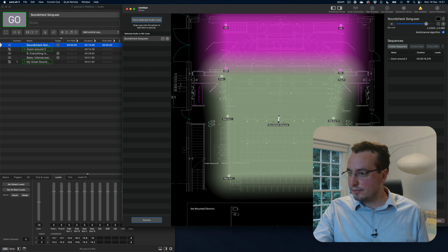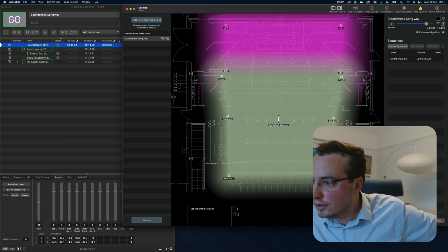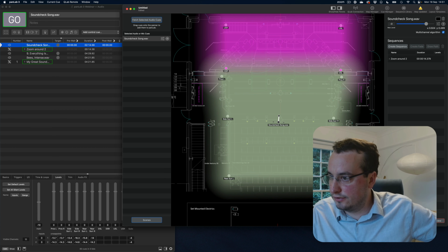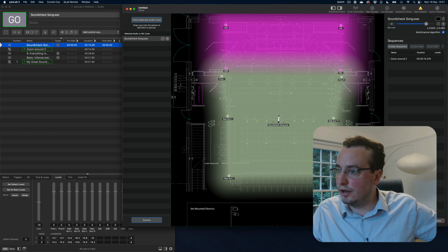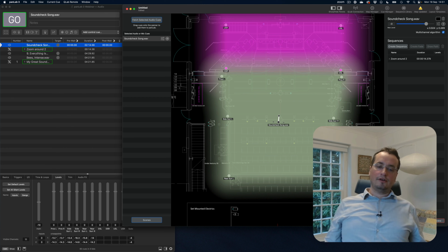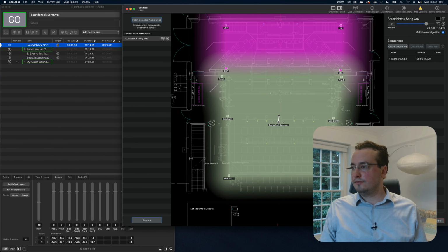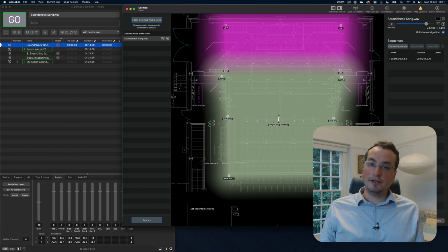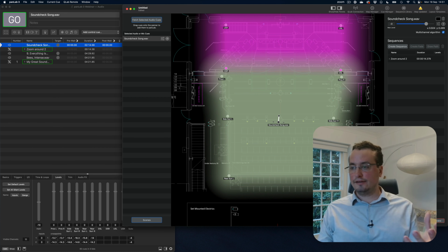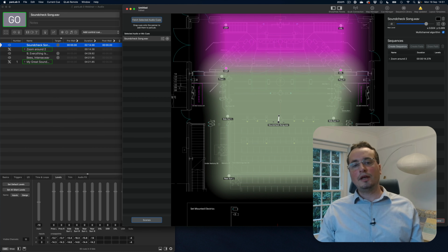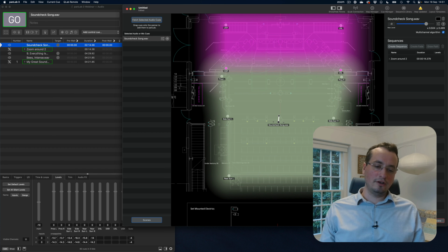Any more questions before we end this up? Okay, yes. Would it be worthy to introduce delay time parameters applied to the cue outputs as well as the audio level parameters within the movement of a sound object? Yeah, good question. So this is purely amplitude-based panning. And there's a very good reason for that, which is that 5-minute setup. As soon as you need to add delay in, you need to know the exact XY coordinates of all of your speakers and the distances between them, and it just becomes a lot more challenging.